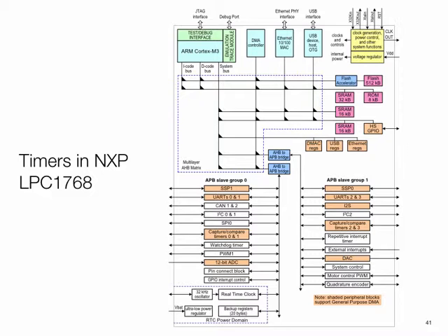So when faced with these kinds of embedded processors, the main thing to get the most out of them is to truly understand what capabilities they provide. This particular chip, I think, also has a DAC, a D2A converter. It has PWM generation. It has a 12-bit, 6-channel ADC. It has a quadrature encoder. Does anyone know what a quadrature encoder is? It has two detectors spaced apart, so you detect 4 times as many pulses. Yeah, it's a sensor for measuring speed.